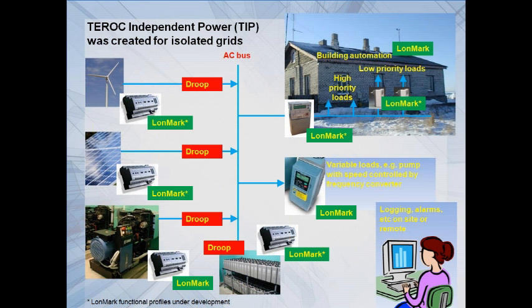For example, how power plants interface with their power to the AC bus. And as I have indicated in this slide, one way to do this and to do the fast load sharing control on the AC bus is to use a principle called droop. It means that frequency variations on the grid determine the power sharing between the units.